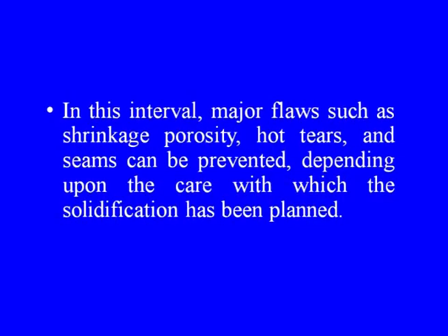Now, let us look into the solidification process. The time taken for solidification of a casting is a relatively brief period in the entire production history. During this short time, the original crystal structure of the casting is formed, which is considered the backbone of the casting, on which many other properties depend. In this interval, major flaws such as shrinkage, porosity, hot tears and seams can be prevented, depending upon the care with which the solidification has been planned.